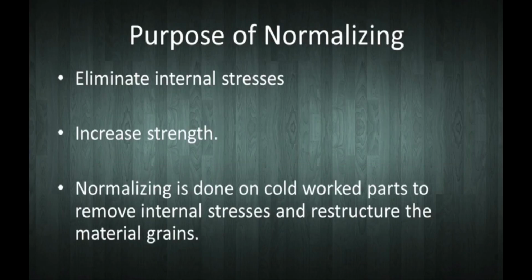Normalizing is used to eliminate internal stresses and increase strength. Normalizing is done on cold worked parts to remove stresses and restructure the material grain so that we can use it in a ductile format or where we require a ductile part.